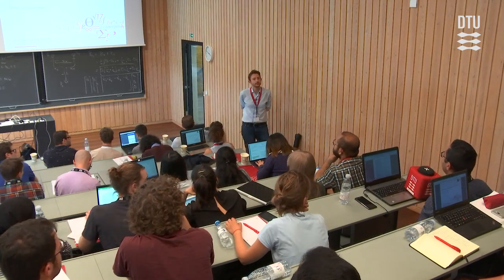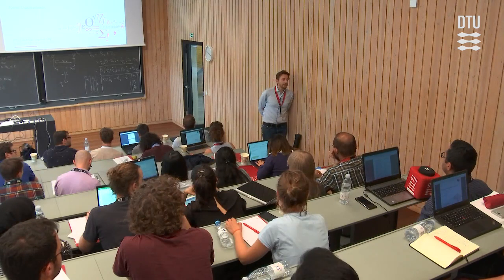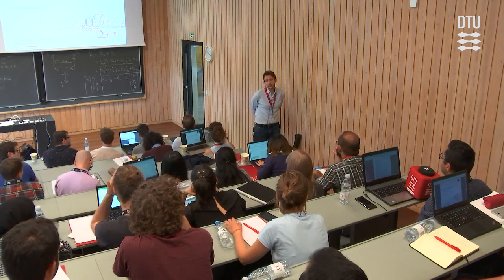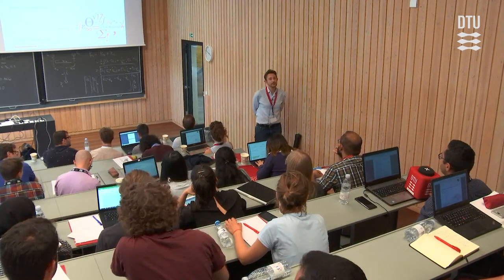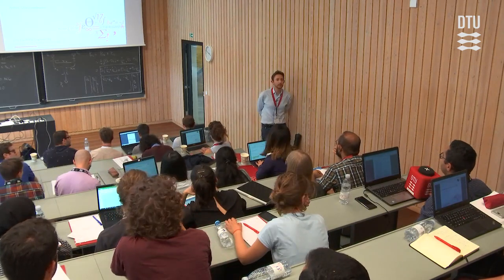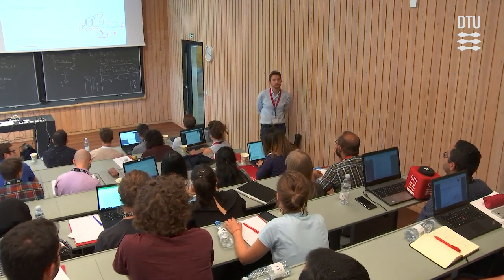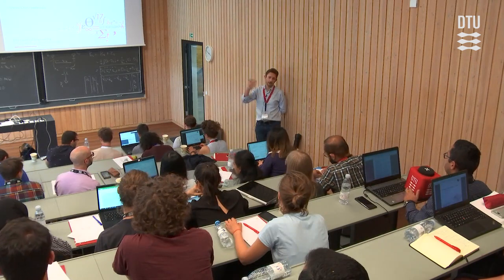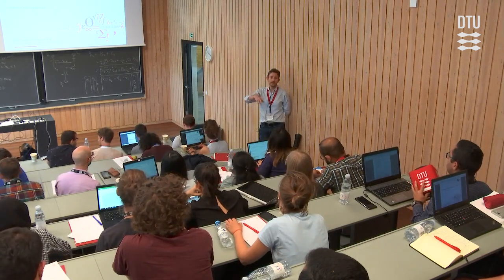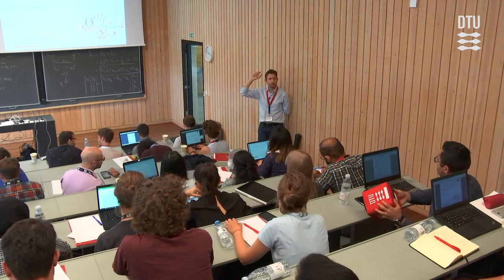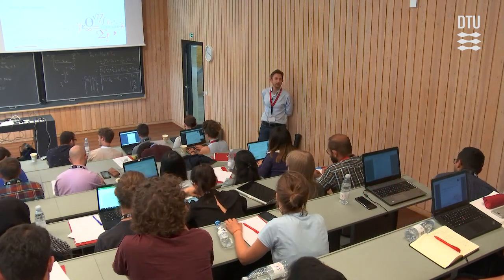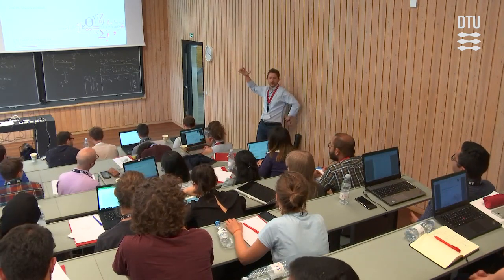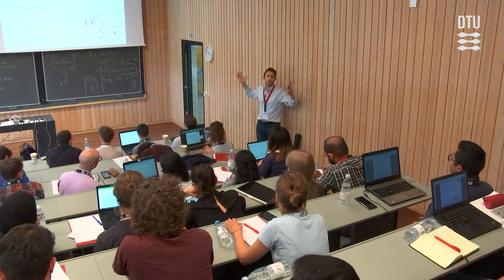And transformers with tap changers? If you have tap changers, then you need voltage. So you need to model voltage, and then you have to go for AC OPF, or let's say that AC OPF would be better suited. You can even approximate that, right? There are also formulations in between. There is a vast literature on every possible type of OPF you can find. These are the two main points, and somewhere in between you can move.